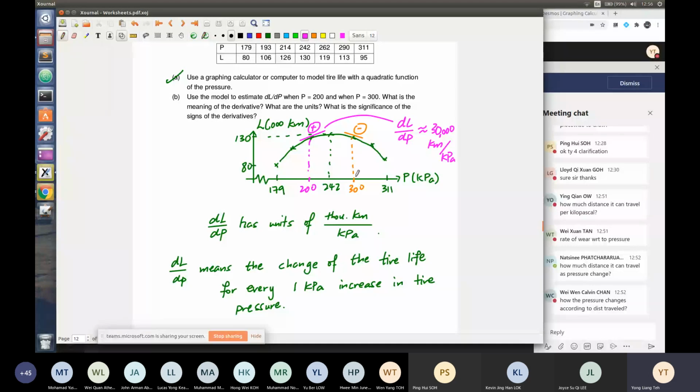You can somewhat reconcile that because, like billiard balls or ball bearings, they actually roll very easily. Because they are very stiff, they're very hard. So their contact with the ground surface is actually very small. When you have very small contact, the resistance on the rolling is lesser. So for a client who wants his car to be very fuel efficient, the client can pump a higher pressure.